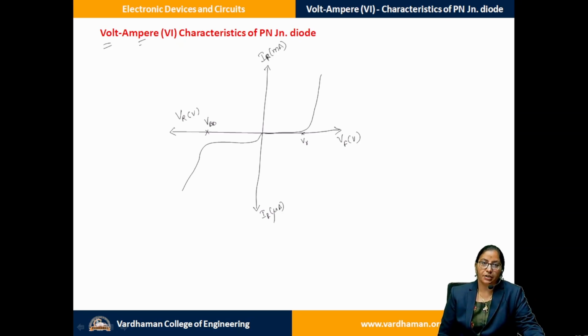Depending on how you are taking your PN junction diode, whether under ideal case or under practical case, the barrier potential and other parameters will be taken as either infinity or zero, depending on whether the resistance has also been considered. So here when we keenly observe, the maximum current conduction happens from this point, that is V gamma. Before it, the current is because of the minority carrier.